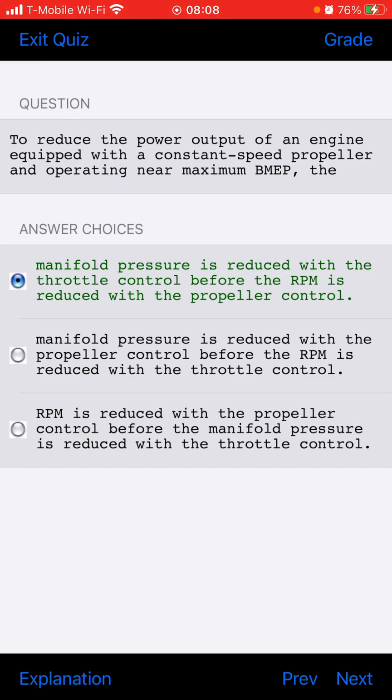So, when rigging any engine control in the aircraft, the stop on the component being actuated must be contacted before the stop in the cockpit. The control linkage has enough spring back in both directions that after the stop on the diverter valve is contacted, the control can be moved in both directions until it contacts the stop in the cockpit.